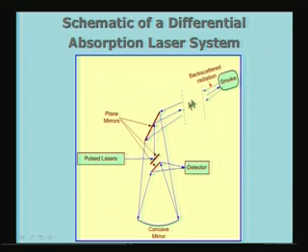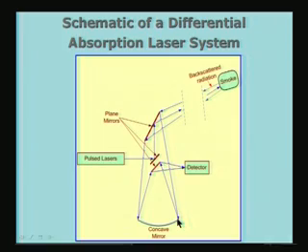The pulse which is going is very strong, but when it returns only a small fraction will be returned, because it will be scattered into all directions and the beam will be expanding, and therefore the intensity is falling, and what is coming back is a small percentage. Therefore, in order to get a sizable signal, I have to gather the radiation over a large area. Therefore, I have a large concave mirror to concentrate all the radiation onto the detector,